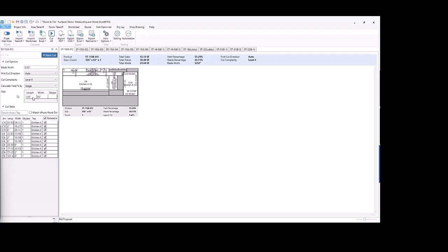Additionally, down here, you can see an area where you can put in your slab information. As you can see here, I've got a slab of 126 inches by 63 inches. This is going to be default. And I don't have a quantity set for this. If I don't have a quantity set, it's telling the software I can use however many I want of this slab. But there may be some situations where you only have a limited amount of that slab.